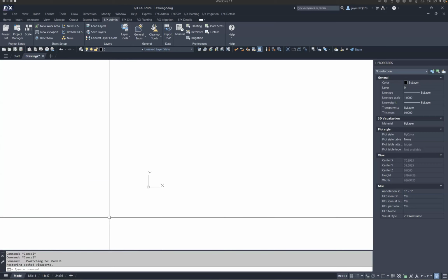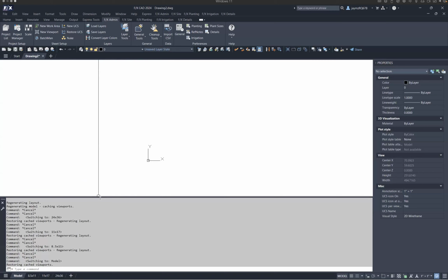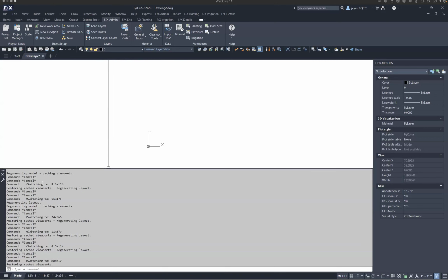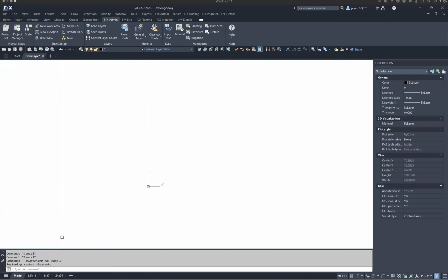Additionally, another recommendation for the command line is you can see that if I hover my cursor over, the cursor changes to this little stretch symbol. I can adjust the height of my command line, and you can see that there's further information shown here. So as you do things in CAD, the command line will scroll up. This text will just keep scrolling. So we want to recommend that you keep at least 3 to 4 lines visible here. You don't have to get crazy, but you want to have a little bit of history just at a glance of what the system is doing.